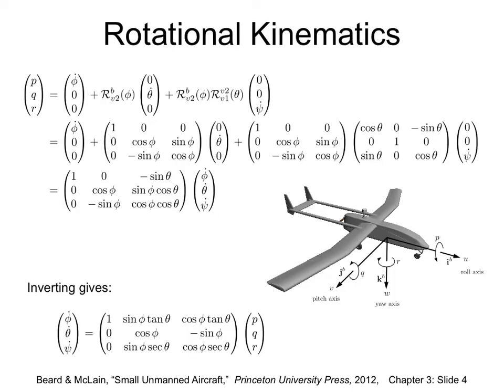Next is a little complicated. So we are trying to get phi dot, theta dot, psi dot, okay? Because all of these angles are defined in different frames, they will undergo different rotations. Because your psi, if you remember, your heading is defined with respect to the vehicle frame, right? How was your heading measured? The UAV moves and the angle is measured from the north axis. The inertial vehicle frame has a north, right? So if I have a UAV, it turns by heading psi. So how is this psi measured? Psi is measured with respect to the vehicle frame's front axis or north axis, right? So this quantity is defined in the north axis.